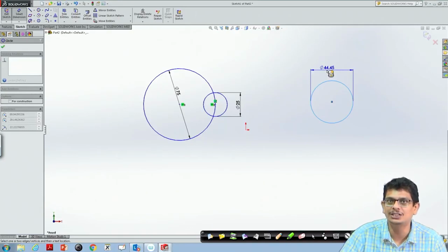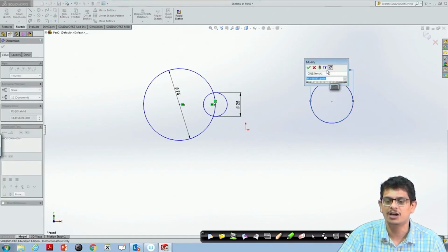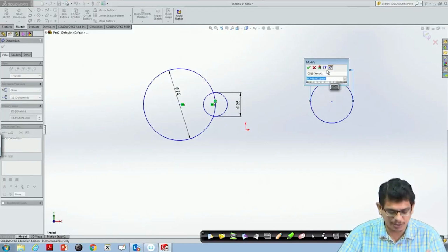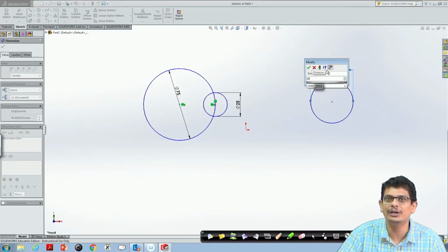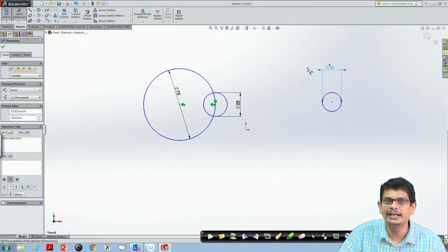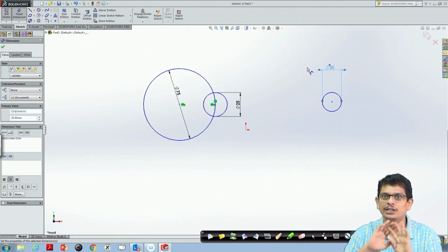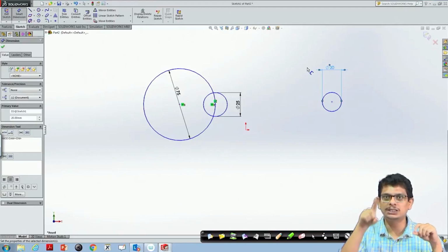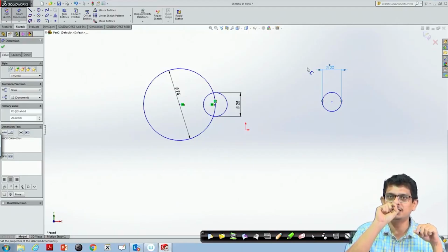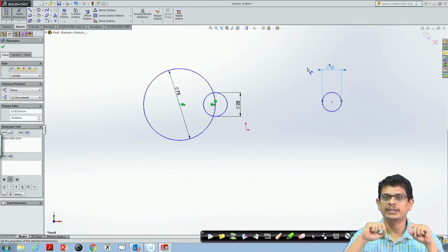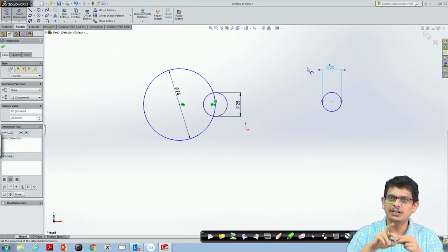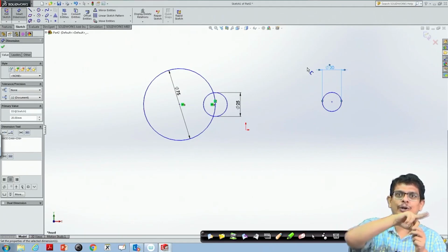Now, if I adjust this first front, it is going to take these dimensions, but let us try whether the dimension really takes care or not. I do not want 44 units, but something like 20 units I would like to specify. Then if I specify 20 units, it is adjusted. Now, those 3 points are not anymore 3 points, but what it has done is, using those 3 points, optimize the equations to fix the center. Now, once the center is constructed, from any point of that, you are going to draw a circle.